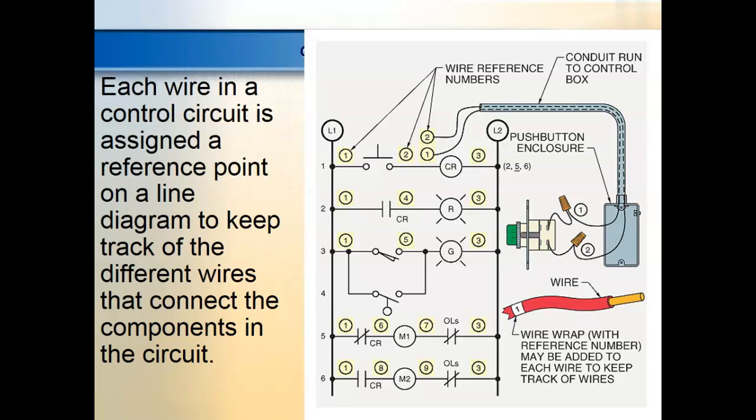So we go through the push button. Every time you go through a device, you change a wire, right? You understand? So one, we go through a device. You don't connect across that device. Somebody's going to do that. They think they've got to make connections on both sides of a push button. Well, what I use, I say it's the car that's between the bumpers. So you got two bumpers, but the bumpers are not connected together. What's between the two bumpers? A car. Well, what's between those two terminals? A switch, right? You understand? So you don't jump across switches. Somebody in this class is going to do that. They think they've got to, but we go through a device, and what did it do? It got a different number.